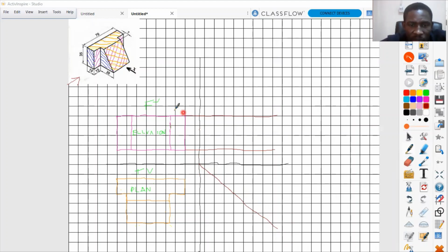Again, I'm using freehand to do all my drawings on the grid. But if you're drawing on a sheet, you'd have to use the help of a set square, the 90-degree edge, with a T-square. So you place a set square on the T-square such that the 45 degrees edge coincides and goes through this center. Then you draw this line. So let's project our top view lines.